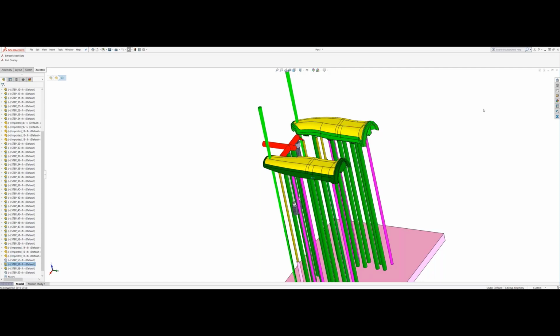All right. And another question, did you have to seal off on the core and cavity because of the holes coming through the ABS part? Yes. Absolutely. Yeah, on the underside, the material will pass through those holes, as John said, through the substrate, and then it will shut off on the core side of the overmold tool.